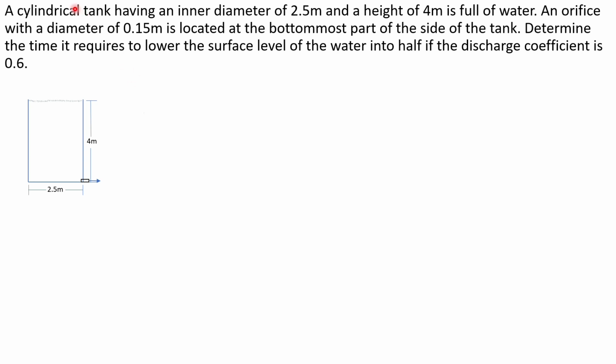Let's start. A cylindrical tank having an inner diameter of 2.5 meters and a height of 4 meters is full of water. An orifice with a diameter of 0.15 meters is located at the bottommost part of the side of the tank. Determine the time it requires to lower the surface level of the water to half if the discharge coefficient is 0.6. So here in our figure,